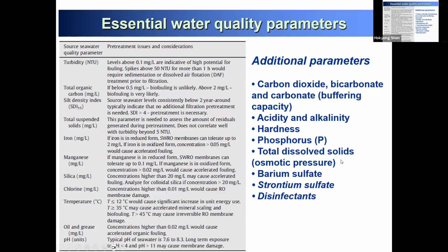And then TDS, temperature, also some scaling, turbidity. They are all important to design. However, for your assignment, your water parameters are already in your scenario appendix. So you can see the basic parameters from the appendix, then utilize that and design a very typical way. You don't have to worry too much about turbidity or manganese or iron because you don't have a chemistry background.